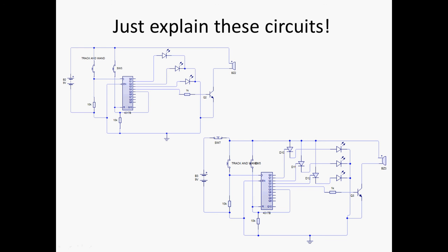if you pause it and look for a difference, and now you've unpaused it, I hope, you will see it's got 1, 2, 3 thyristors. So in this circuit, every time I lose a life, the lights will not only light, but they will stay on, so all 3 lives will stay illuminated as I lose them.